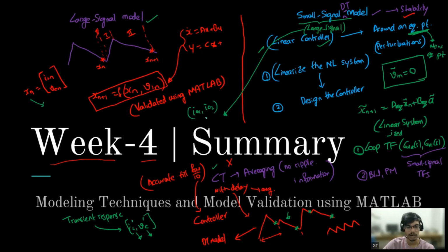But our small signal works on the perturbation, so we are not considering very big step changes. We assume that the perturbation is small, and that's why we are linearizing the controller. And of course, since we assume that the perturbation is small, when we give a large step response, it might not capture accurately. So for that we have to go for advanced controller techniques. But as far as small steps are concerned, it should be fine. Okay, sir.